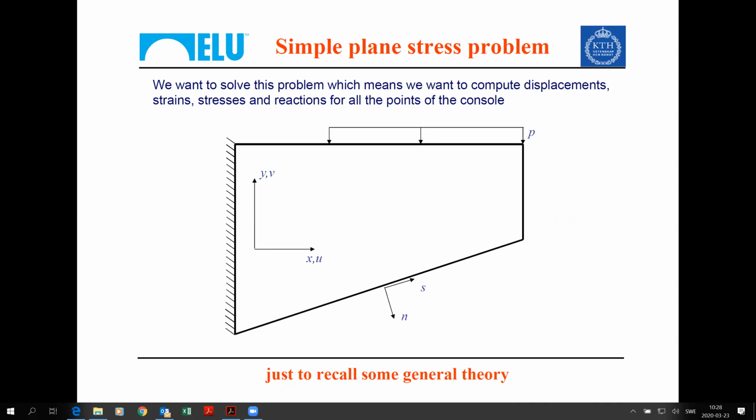The idea is that we want a solution for this particular cantilever structure, shown on the slide, given the h/L ratio, so the height of the cantilever is comparable to its span. We wouldn't expect this to behave like a beam, and we will need to go to a plane stress solution.